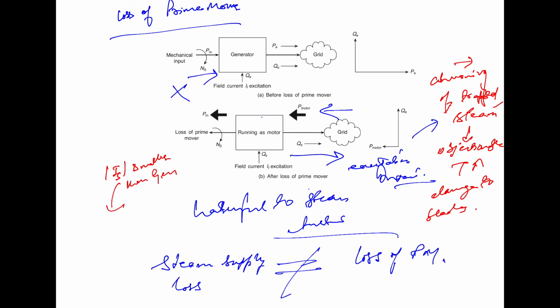However, it goes a phase shift of 180 degree. Now, from this what we conclude is that if we use the directional relay with the maximum torque angle of 180 degree using the phase angle conventions, then it would detect the loss of prime mover as the current phasor would reverse and enter the trip region.